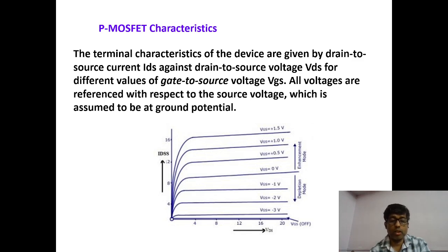So actually what will happen? Okay, as the figures show, substantial drain current flows at VGS equals 0, and VGS can be positive or negative in the former, but VGS is negative in the latter.